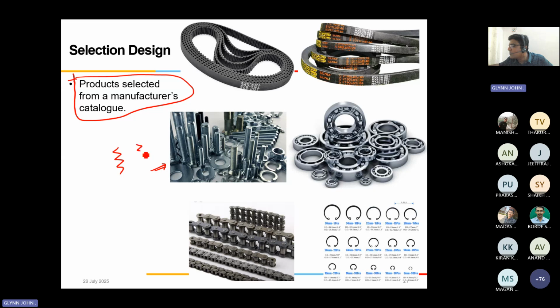they will actually give you what is called the stress area, right? So that means you take this area, it is called the stress area. That stress area for that fastener will be given in the catalog. So while performing your calculations, you will be using an area for stress calculation. So if you're choosing, for example, an M8 bolt, the stress area will be given in the catalog. You take that value from the catalog, you perform calculations.